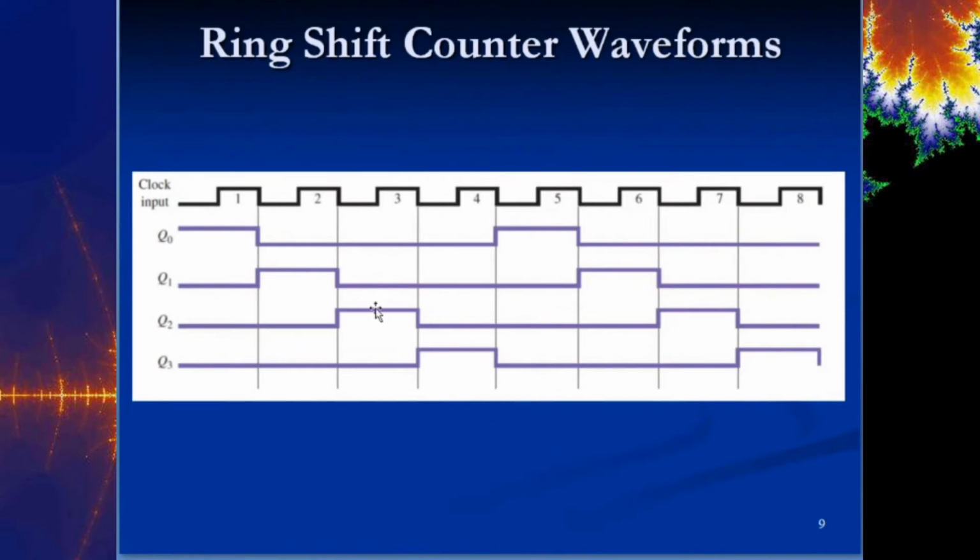So kind of neat things that you can do with it, but it allows you to do things in a sequence, because after Q0 is activated, the next one to activate is Q1, and you know that the next one to activate is Q2. So you can see here, it is kind of like a synchronous counter, except it's not producing a true binary output, but it's still producing a defined count. So you could look at this like it has a modulus to some degree, okay? It's not exactly the same as the modulus of a ripple counter, but it's still repeatable. You know how many clock cycles it takes to repeat, however many bits there are.